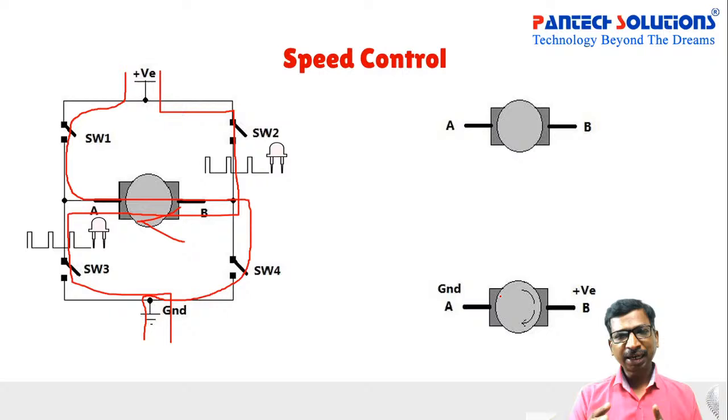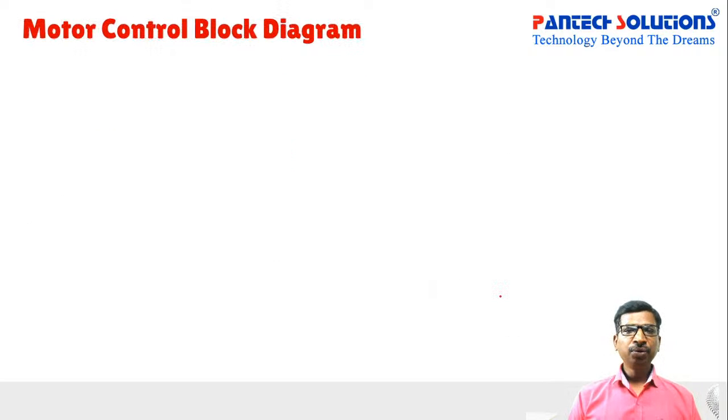During that transient period, all the parameters of the motor will not be in steady state. They will change their behavior on a time basis. To avoid huge fluctuations during the transient period, people use a soft starter method. In that aspect, soft starters came into the picture.